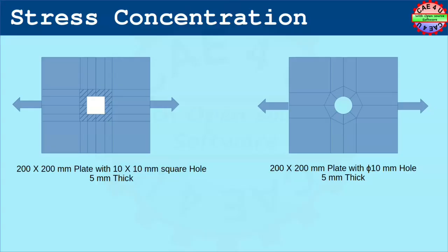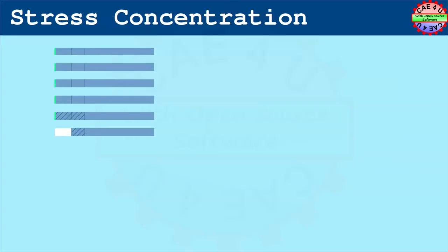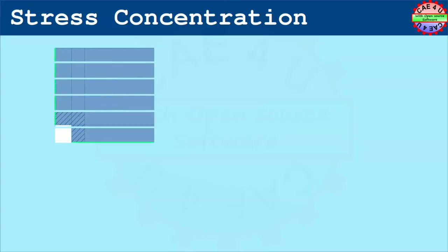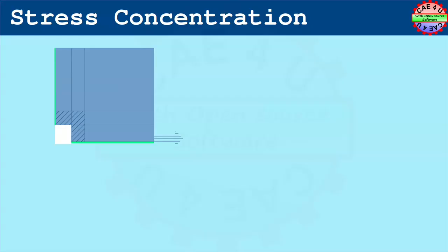The lines shown are the partition lines of the geometry for creating structured mesh, and also we provide a buffer zone near the holes so that we will be able to see the effect of mesh refinement. Looking at these cases closely, we observe that the geometry and the loading, along with the boundary condition, exhibit 1/4 symmetry. So it is sufficient to just model 1/4 of the geometry and adjust the loading and boundary conditions accordingly.